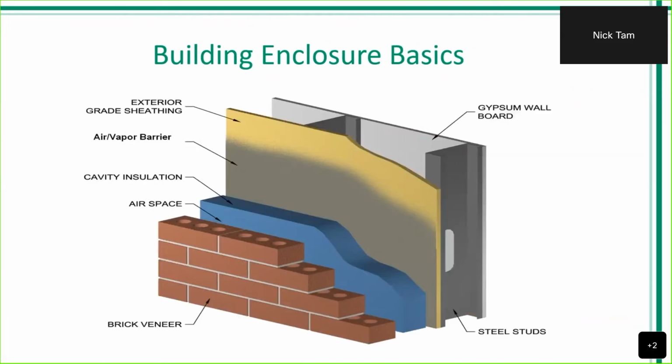This is an example of a lower costing wall that we see a lot in our projects today. This is going to be a steel studded structure with a sheathing attachment. But with this, compared to the CMU wall, one thing that will be lacking is the moisture sink that can be provided by the concrete block. But we still follow up with those 4 control layers like we would on the other backup wall, and we still have what we call a really good building envelope here.